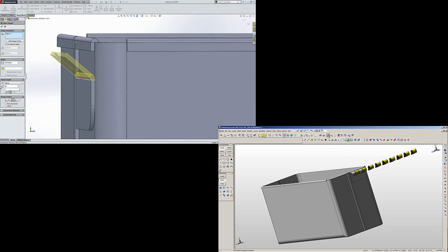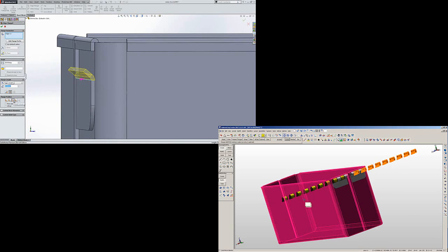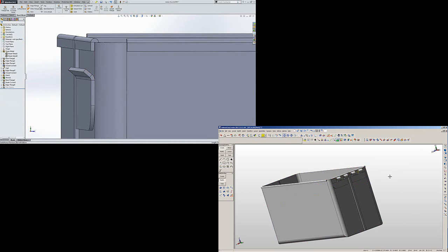We're going to have an end condition of 4mm, and that's going to be from the inner virtual sharp, which is from this edge here, to the imaginary internal virtual sharp, which is where this edge and this up edge here meet in the middle here. We're going to have that bent outside, so we can accept that.